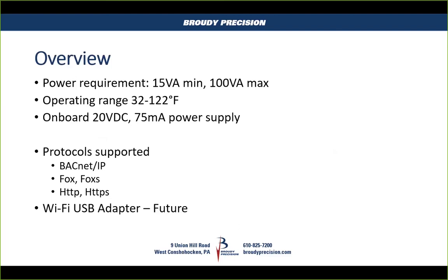For protocols supported, you have BACnet IP, and again, client and server, Fox, FoxS, so you've got secure Fox, HTTP, and you have HTTPS for your web server. And in the future, they're going to be adding a USB Wi-Fi adapter, so that you'll be able to have these controllers go Wi-Fi.